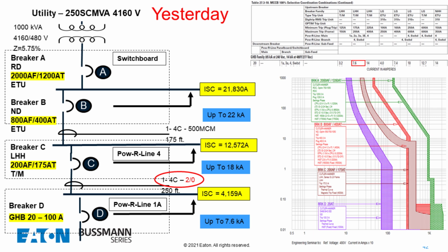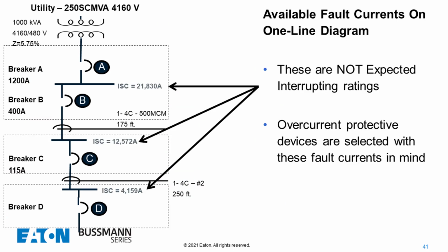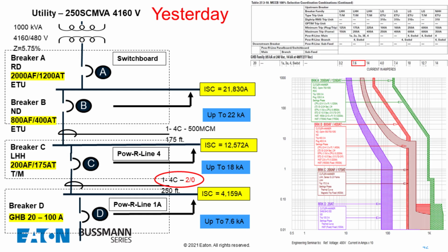But what happened? Remember, C was at 115 when we first designed it. Well, we couldn't use a 115 amp breaker. So let me go back a little bit to show you. We used a 115 amp breaker, or a 100 amp breaker, to feed this. I see a lot of 100 amp breakers feeding this main lug only panel, and in this case we can't do that. And what conductors would we use? A number 2 or a number 3 if it was a 100 amp breaker.